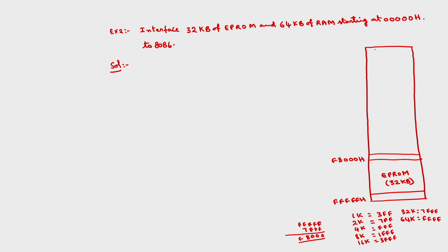And the RAM, it is given that you have to connect at the starting of the total 1 megabyte of memory, so 00000H. And the capacity is 64 kilobytes, so the ending address will be 0FFFFH. This is the RAM of capacity 64 kilobytes.